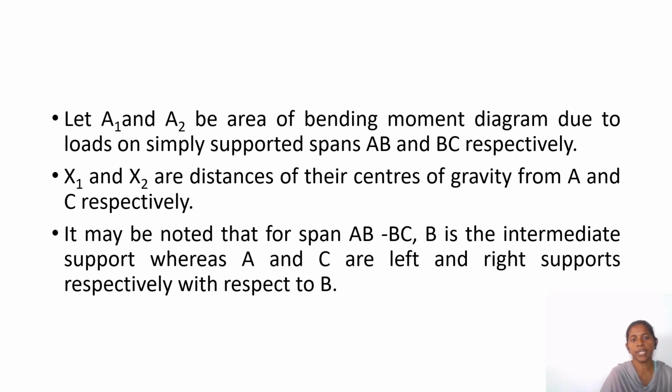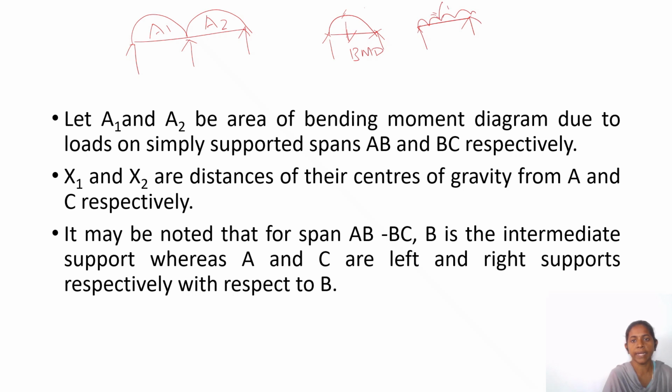So A1, A2 are the areas of the bending moment diagram due to the loads on simply supported span ABC. We have considered the beam ABC and drawn the areas A1 and A2 of the bending moment diagram, considered as a simply supported bending moment diagram. When it is a parabola for a simply supported beam loaded with a UDL of W, then the bending moment will be a parabola.